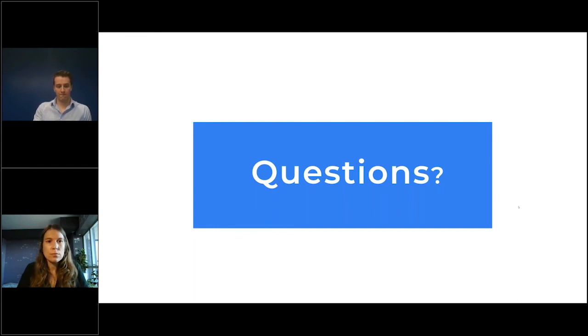Awesome, thank you, Connor. Kirsten, we'll throw this one your way. Are there any other CAMWorks modules available that we haven't shown so far today? Yes, there are a few. So if you've got a wire EDM machine, CAMWorks has an additional module just for wire EDM. That's 2-axis and 4-axis EDM machines. And actually in 2021, they just released a professional version of the software, which significantly speeds up programming. We've also got a nesting module, called NestingWorks, and this would work with CAMWorks and SOLIDWORKS CAM, but it's also compatible with other CAM systems as well.